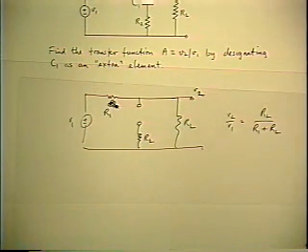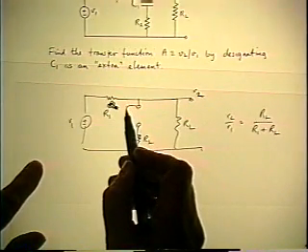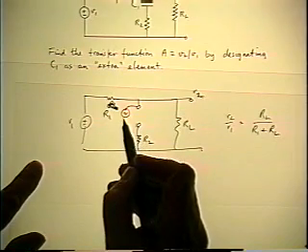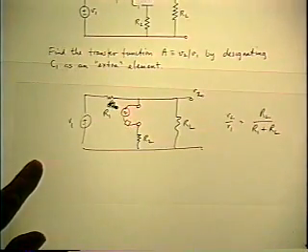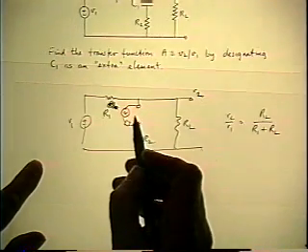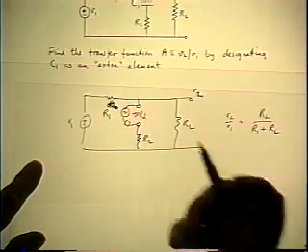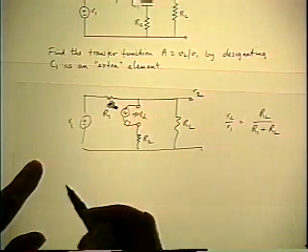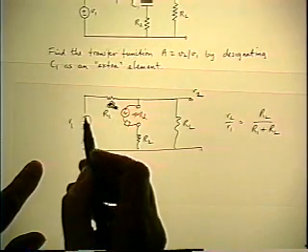Now we calculate the two driving point resistances. So we apply an external source, doesn't matter what the source is, and we calculate RD. I'll immediately write RD now instead of ZD because we know it's going to be a resistance, and it's a single injection calculation, and you make the V1 0.